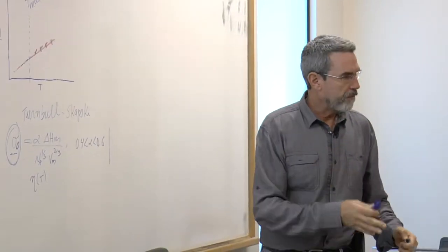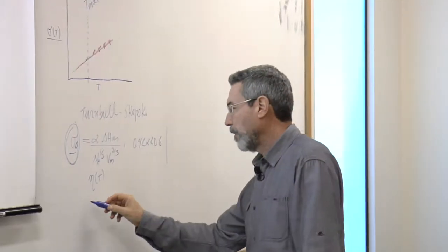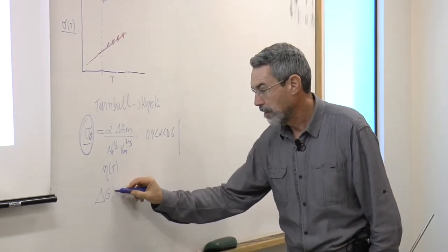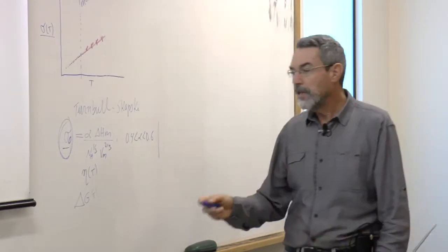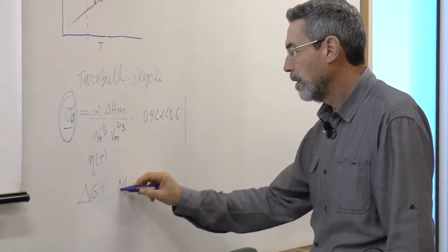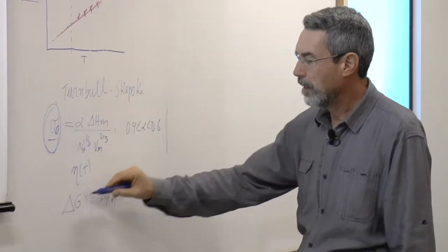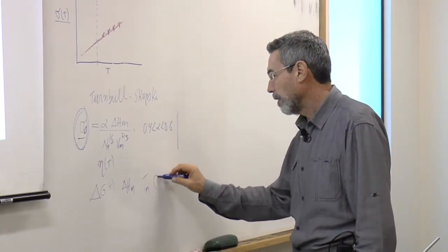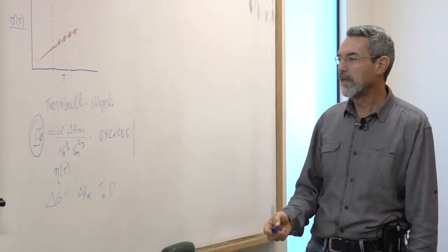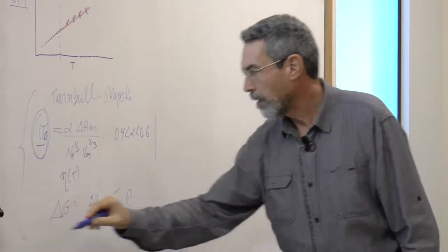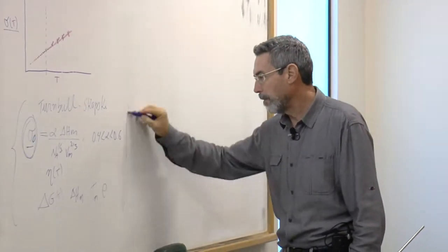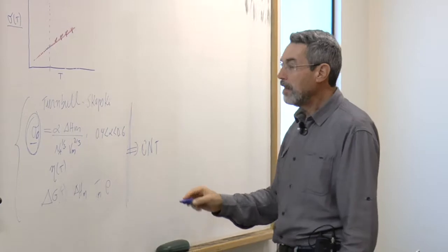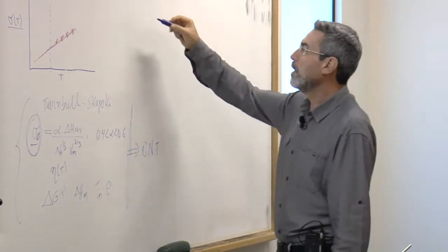You have seen in previous lectures, and you have done your homework, that you can also measure and calculate delta G as a function of T from the specific heats. And then you need what? The heat of melting, delta HM, which comes here and comes here, the melting point and so on, some other thermodynamic properties, the density of the glass, the density of the crystal. With these parameters, we can plug all of them into the classical nucleation theory and predict a nucleation rate curve.